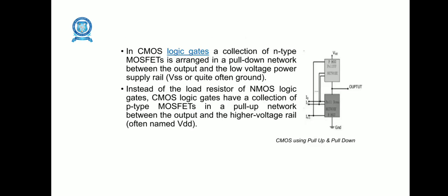So you can see here, if both the p-type and the n-type transistor have their gates connected to the same input, the p-type MOSFET will be on when the n-type MOSFET is off, and vice versa. These networks are arranged to be on or off for any input pattern given. CMOS can offer relatively high speed, low power dissipation, high noise margin in both states, and it can operate over a wide range of source and input voltages, provided the source voltage is fixed. Furthermore, for a better understanding of the complementary metal oxide semiconductor working principle, we have to discuss the CMOS logic gates briefly.